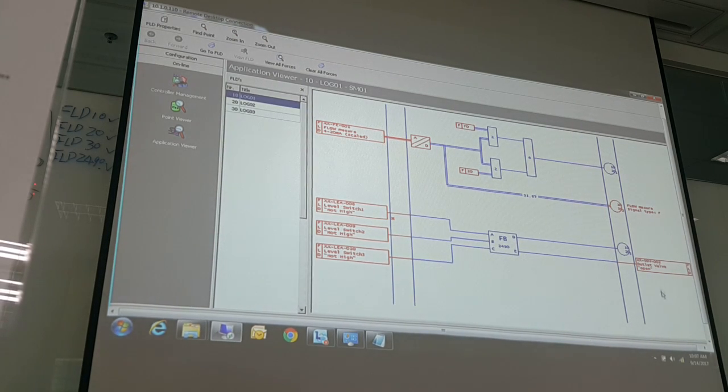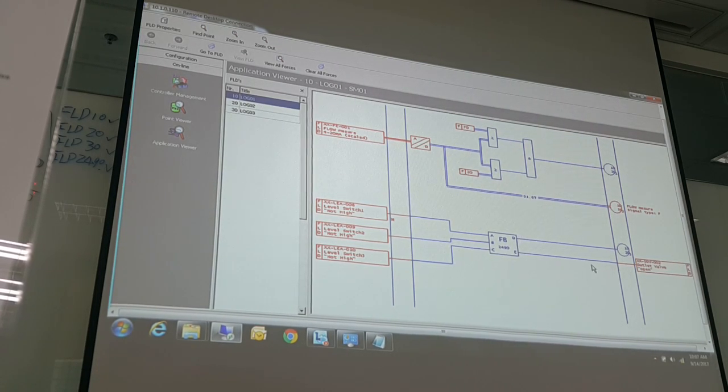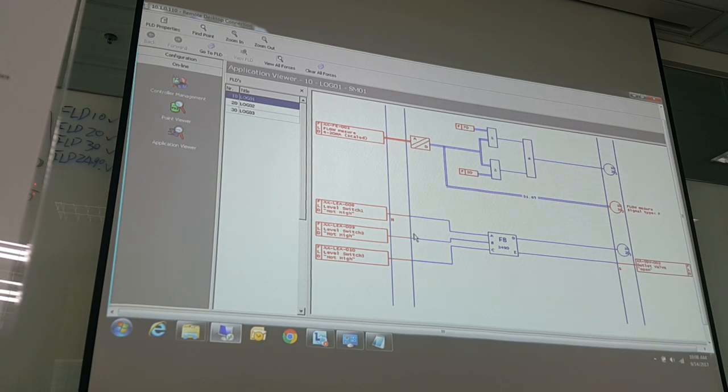And if it is a DO, the current state of the DO is what? It is logic 1, right? And I want to force it to low. And the L between these two lines is also the state outside. So you just remember this is the state outside of the system. And if this is different from this, that means you gave the force.